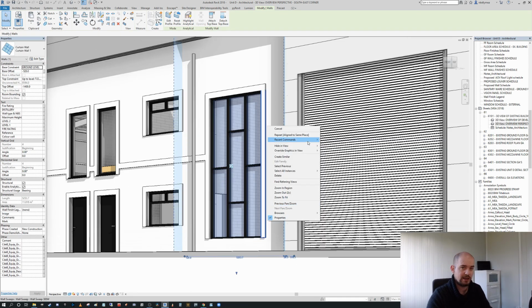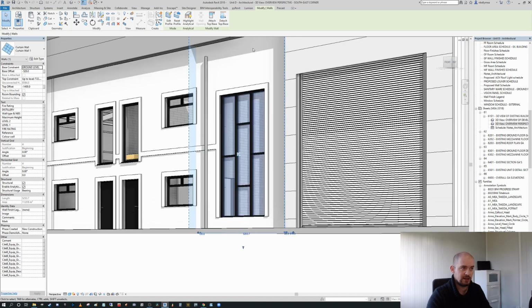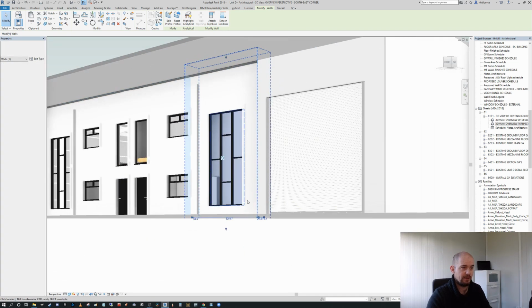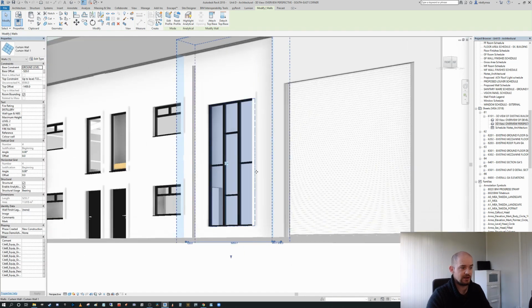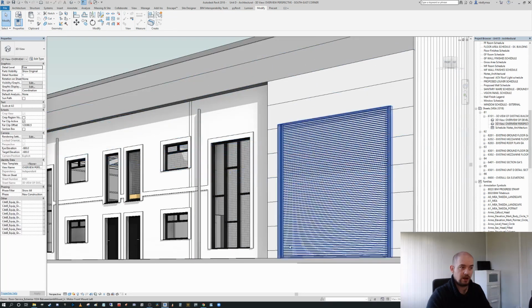As you can see, this has been edited to suit the opening, and it's tied actually to the top level. There is reason for this. This isn't lazy modeling. I actually have these locked to the constraints of the bounding wall, so should they change, the overall dimensions of this curtain wall will flex in a way that I'd be happy with, okay.